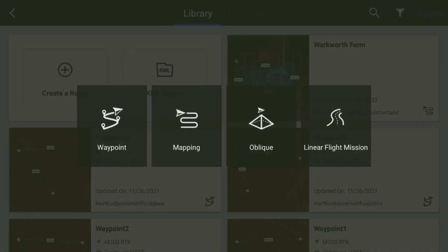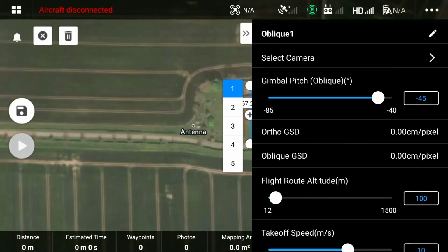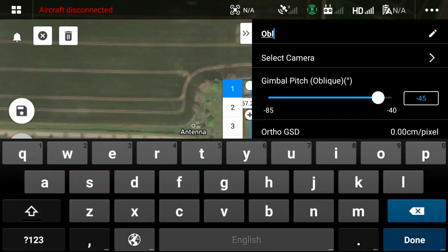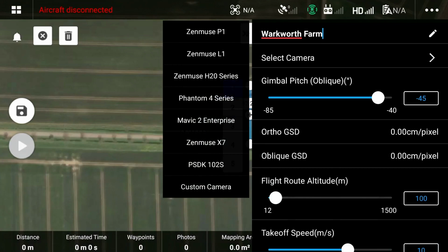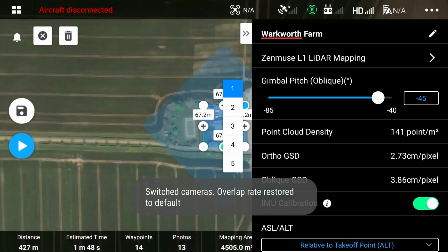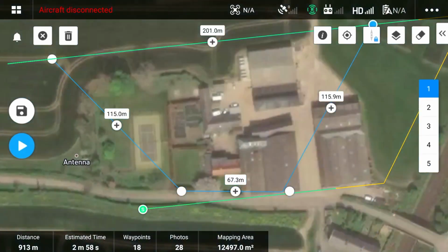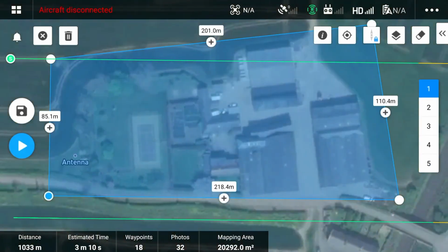For environments with significant terrain undulations or 3D structures, standard Nadir data will not provide comprehensive point cloud densities on the sides of facades. Therefore, the L1 sensor angle must be set at an oblique angle. In DJI Pilot, oblique missions are split into 5 sub-missions. The first of those will provide Nadir data capture directly over the area of interest, whereas the subsequent 4 missions displace the flight path in each of the 4 directions: east, west, south and north.